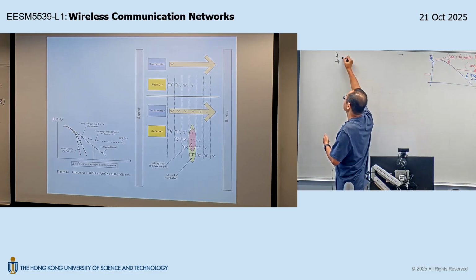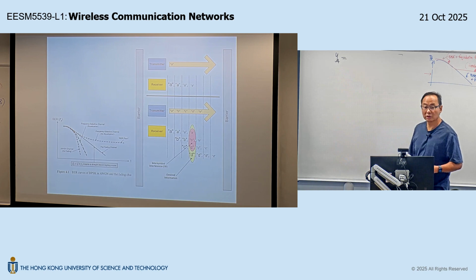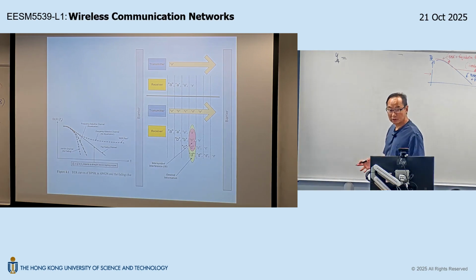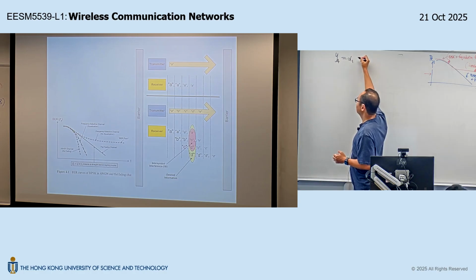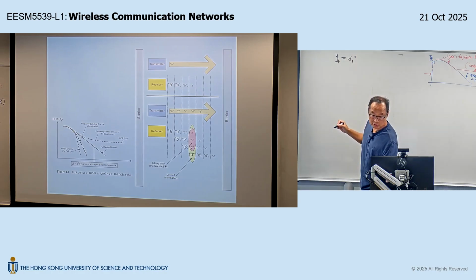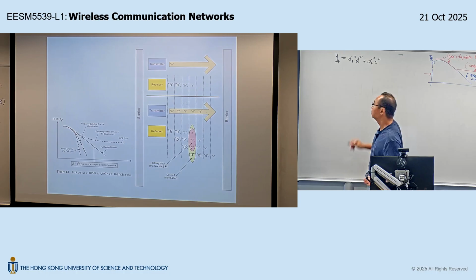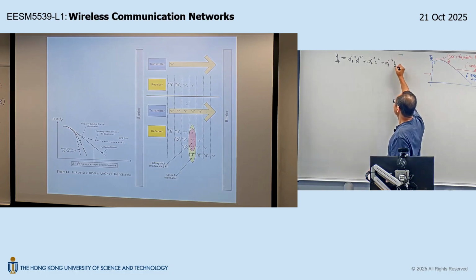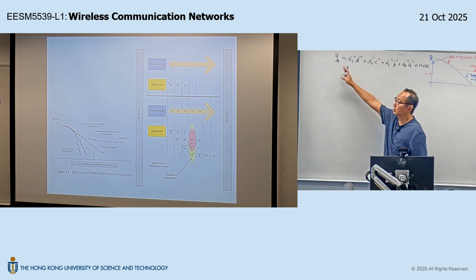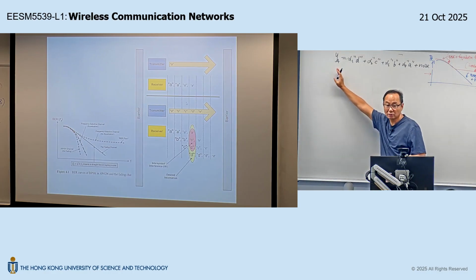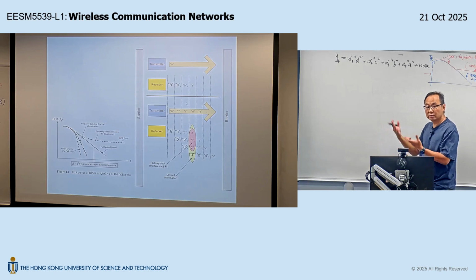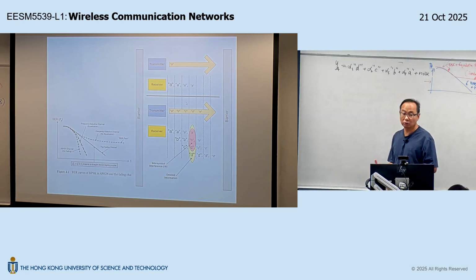Let's say Y4, denoting the 4th time slot observation. This Y4 consists of multiple copies, right? Alpha 1 times the immediately transmitted symbol D, plus alpha 2 times C. C is the previously transmitted symbol, right? Plus alpha 3 times B, plus alpha 4 times A, and then plus noise. Is that okay? So that would be the composition of this observation, Y4. So again, from this composition, we try to identify which terms are good, which terms are bad.